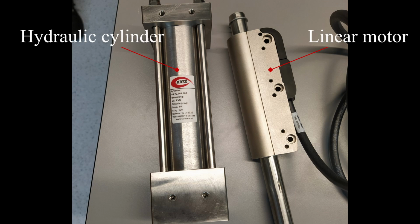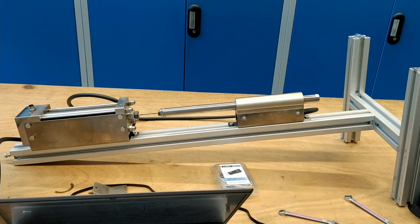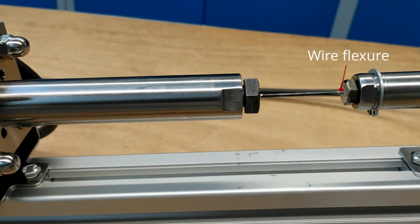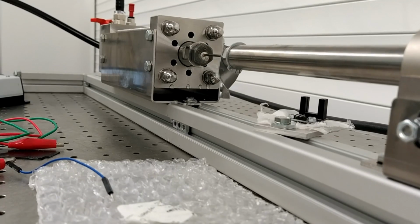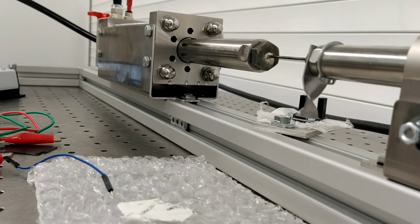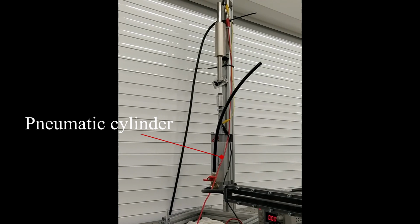To create the liquid flow I used a hydraulic cylinder. The cylinder is driven with a linear motor made by Linmot. The Linmot is connected to the cylinder via a wire flexure to circumvent any misalignment errors. The Linmot is a great motor with precise position and speed control. This is useful for creating a constant volumetric flow rate without pressure variations, which would be present with a centrifugal pump. The hydraulic cylinder needed to be replaced since it started leaking. It was replaced with a pneumatic cylinder since that was readily available.